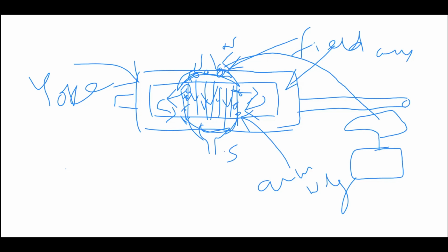It has copper segments. So the rectified armature winding is connected to the commutator. Now the rectified current is passed from the commutator to the load circuit via the brushes. Suppose this is the rotor. Now this is the commutator, which I have shown you again, and these are the brushes. These are the same brushes we show in the DC machine, both DC motor and generator.